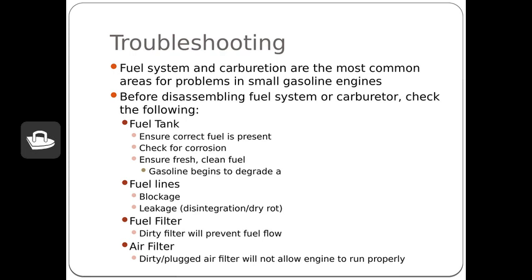We worked and tried to figure things out. And after not taking the advice I'm giving you now, starting to tear carburetors apart and everything else, we pulled the fuel lines, and somehow a June bug had gotten into the gas tank. Maybe it was in the gas can, who knows? But it got in there and ended up getting partially into the fuel line and blocked it. So you just never know. After that, we got that beetle out of there, and she started right up.